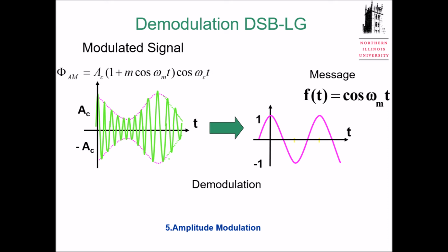So last time we mentioned, once you choose your R and C very cleverly, when the signal goes up, you charge your capacitor. When the signal goes down, it will be discharged slowly. So we go up and down to catch this envelope. Next time when my signal goes up again, it will charge my C again.